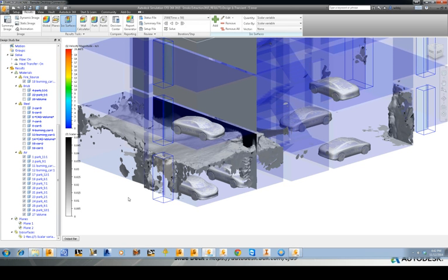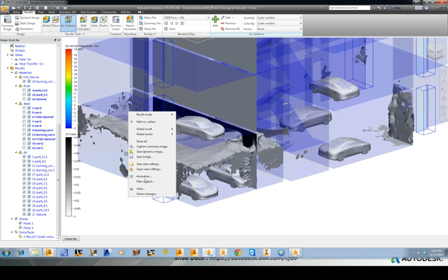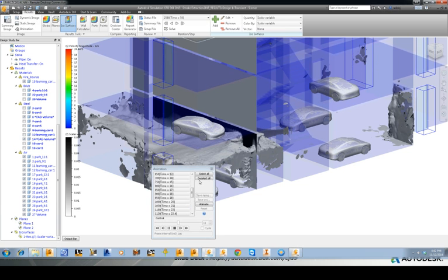That's a really good point. One thing we didn't talk about actually is animations. We can do that on this model. At any point, once you're within your results, if you want to animate over time, we can just switch to animation and then select the time steps. I won't select them all because it will take quite a long time. Then press animate.